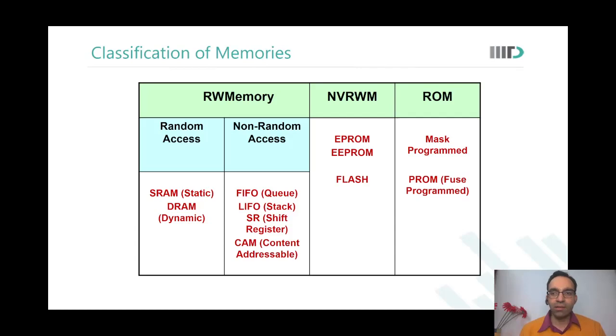Because then if I'm sending 1 gigabyte of data from one part of the chip, and the other part of the chip can accept only 800 megabytes of data, then 200 megabytes of data we end up losing. So we understand that not every cycle would require data transfer, and therefore we can still operate two different parts of the chip at different frequencies.